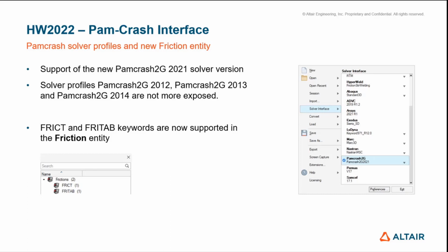Also, as a cleanup of PAM-CRASH versions which are today not really used, and in order to focus more on the latest and greatest profiles, the profiles 2012, 13, and 14 are not exposed anymore, which doesn't mean that you cannot read those decks in HyperWorks. It is just that those profiles will not be exposed anymore, but you have access to all the latest and greatest profiles, which are the ones used on the market today.